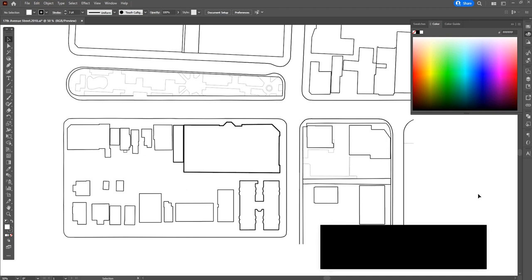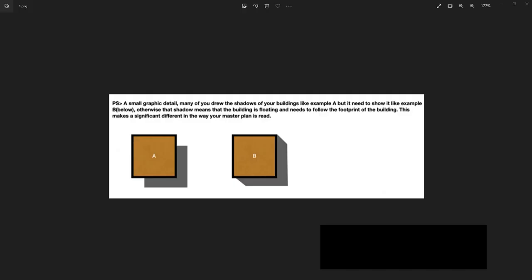Now let's take a moment to discuss how shadows are projected in Illustrator. Traditional shadow tools in graphics programs like this one might encourage you to project a shadow like the one you see in shape A here. But when you think about it, this wouldn't be realistic for our plan view because our plan view is reflecting a shadow from a built mass. It would project a shadow from the faces we're not able to see in plan, like you see in shape B here. It's not projecting from a flat face like we see in shape A. It's projecting from built walls that are invisible from this perspective in plan view, but still need to be shown anyway. So I'm going to show you how we accomplish this in Illustrator.